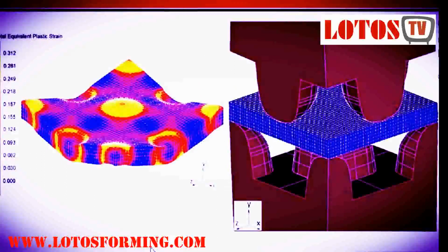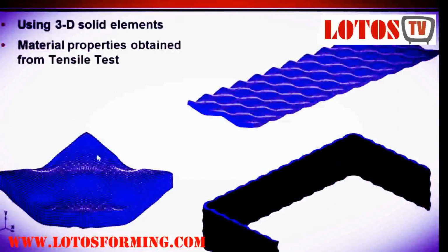And then the next step is that we will use this dimple geometry only, not the data, and then we develop the dimple strip or the end products from these generic elements, as I can show here. We use the dimple and then generate the dimple strip, as we can see on the right, and then we can cold-form it into a section. In this example is the channel section, as I show here, using this approach.